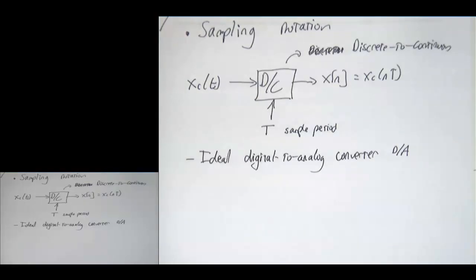Any comments on that? Questions? So you're putting in this continuous signal, and you're getting out a discrete signal? Yep. Yeah, so it's sort of a weird block. If we were going to characterize this from a signals and systems perspective, it's a time varying system, because if you shift the input signal, the output totally changes. It doesn't shift. And linearity is satisfied. But yeah, it's a weird kind of system block. So continuous comes in, discrete comes out.